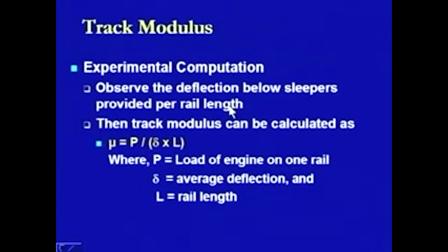Now here, either we take a unit length of the rail section, and then on that unit length we take up the number of sleepers being provided. But this is a little difficult because of the spacing of the sleepers. We are not providing the sleepers adjacent to each other or abutting to each other. In that sense, it is easier to compute based on the total section of the rail which is being manufactured by the company, which is roughly around 12 to 13 meters, and for that rail length there are a number of sleepers being provided.